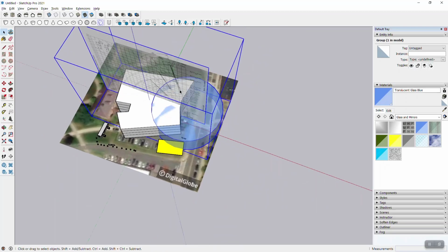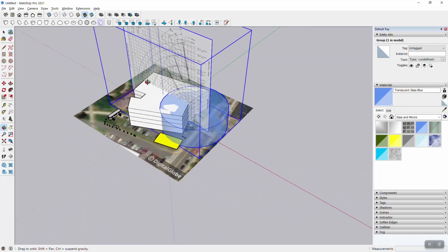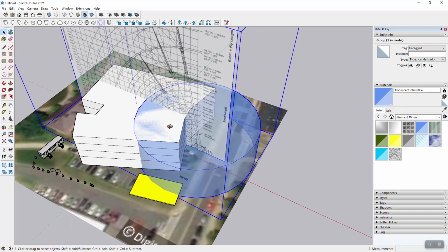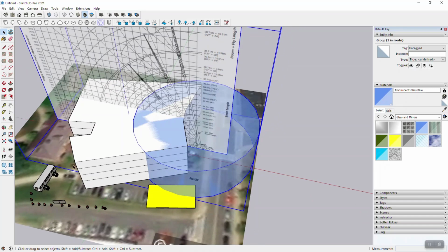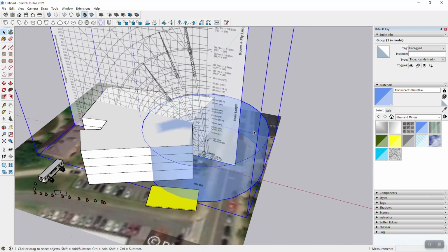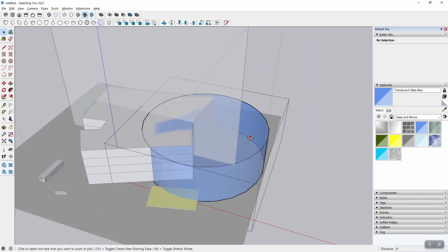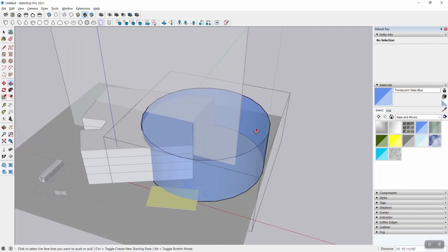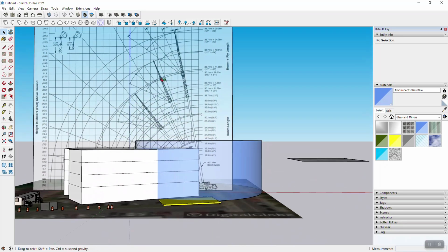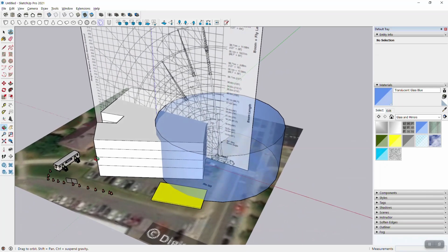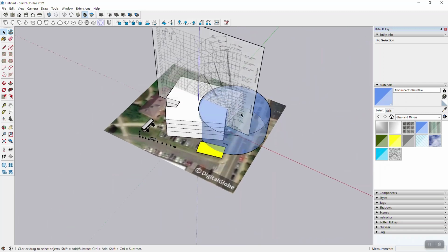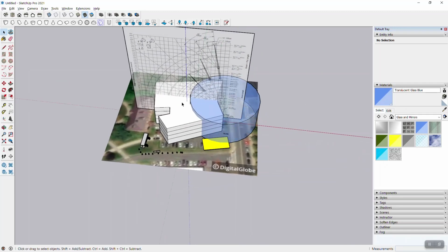And then again, the neat thing about this approach is now you have a reach and a range that you can create as overlapping circles, multiple locations and so on and so forth, and you can work with that. And I do get some Z fighting, so I'm just going to go in here, extrude that a little up, and now that looks much better. So there's my assumed crane range. So that's another way you can plan site logistics very quickly, actually.